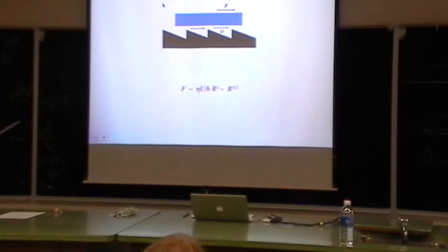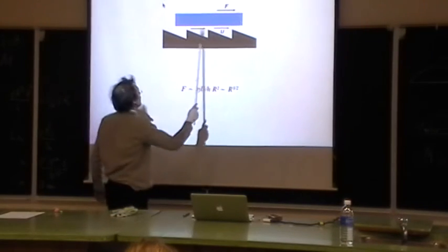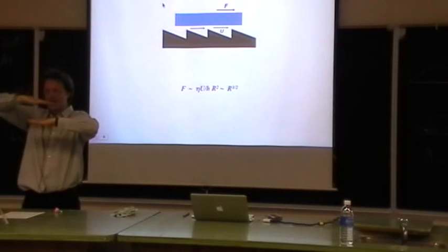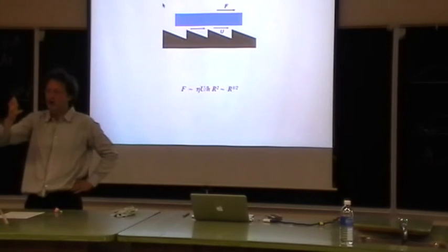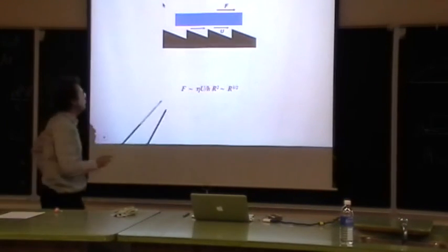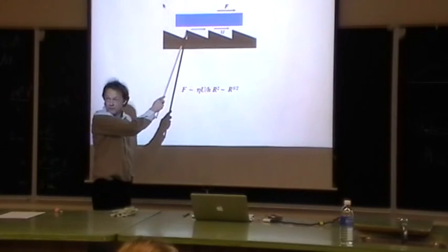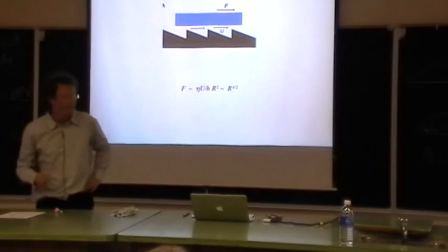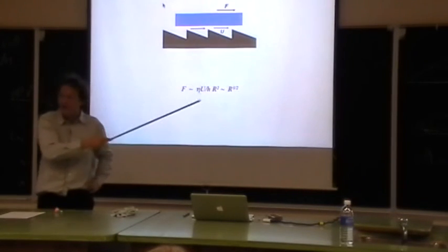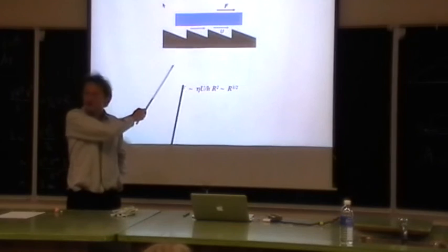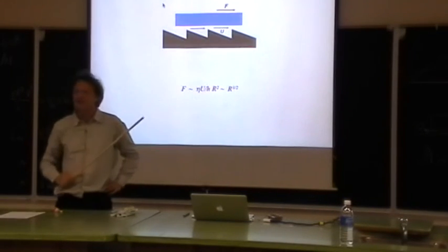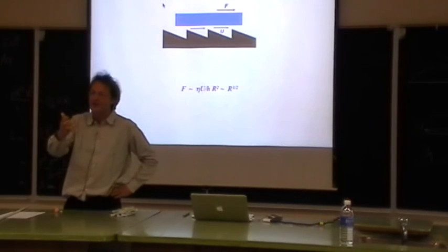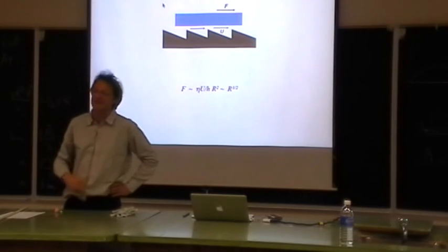He took a flat piece of solid here, a ratchet, and he oscillated the flat piece like this, okay? And there is a critical Reynolds number, above which you see a flow in the direction that I assumed previously. But this critical Reynolds number is 100. And now, once you measure everything, you can calculate the Reynolds number in this experiment. It is of the order 1. So it's not enough to induce the flow in the direction. So it's not inertial enough, if you want.